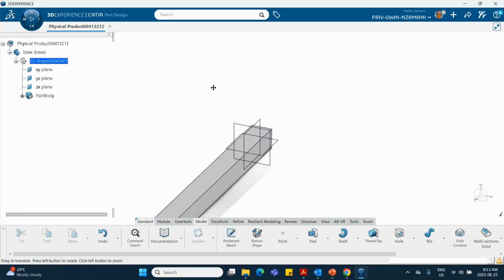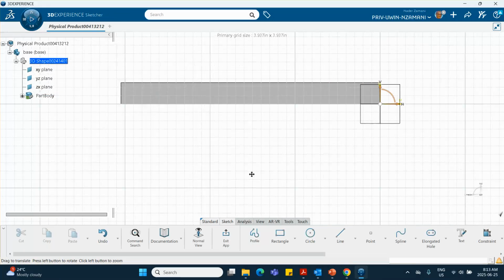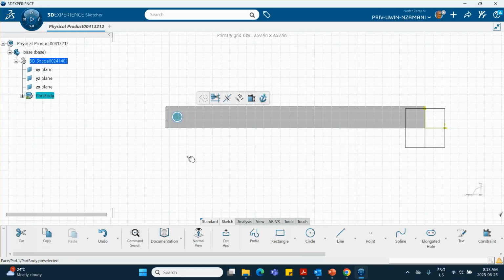Okay, then I'm going to make that pin on the right side of this face. The location of it, although of course it affects some stuff, but it's not critical for our purpose. And I'll just randomly select at this point. Let me just dimension these things. So this is going to be radius 0.25.